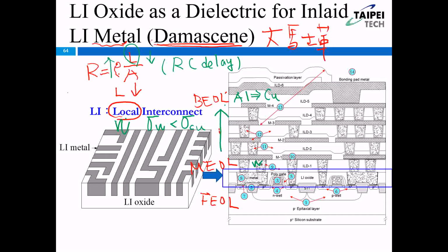Connect: you want to connect all of these electrical signals by using the metal line. So interconnect will be a metal material, just like the tungsten we mentioned here, or the copper, all of these metal lines. M4 is the fourth metal layer. M4, M5, M6 are the metal layers. We call all of it the interconnect.